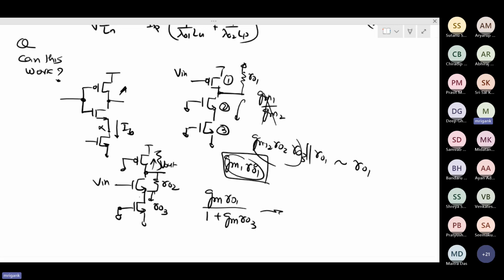But you have some AC coupling. So what is the DC potential here and here? Vin DC and Vout DC are not well defined. How will you solve for Vin DC? There is no way to solve. It is a floating node. Is that clear?